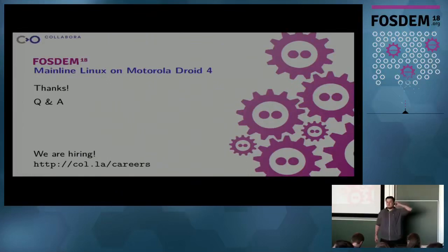Have you looked into the bootloader side, especially U-Boot? Do you know if the version of the OMAP stock that's used on the phone is the high security version that you cannot run your own first bootloader on, or is it the general purpose version where you can actually do that? So are there signing keys and is it locked?